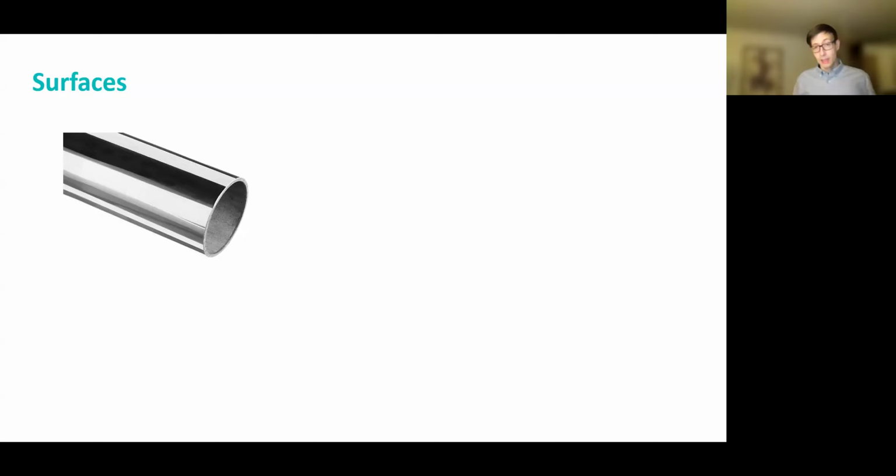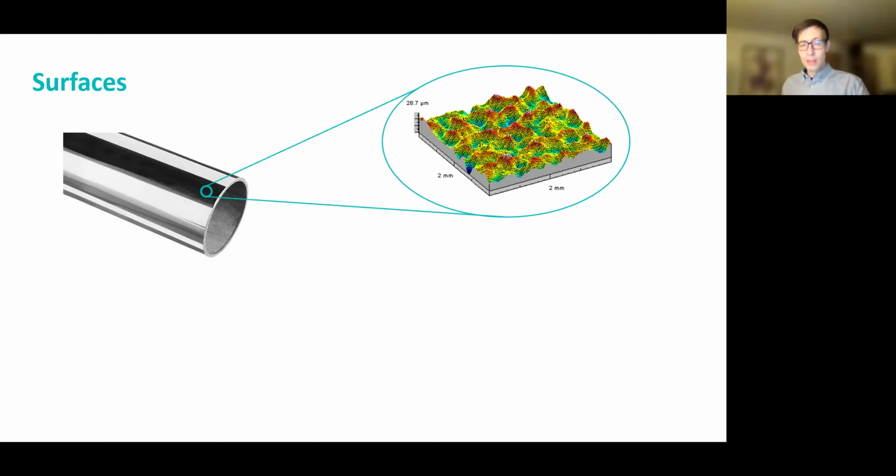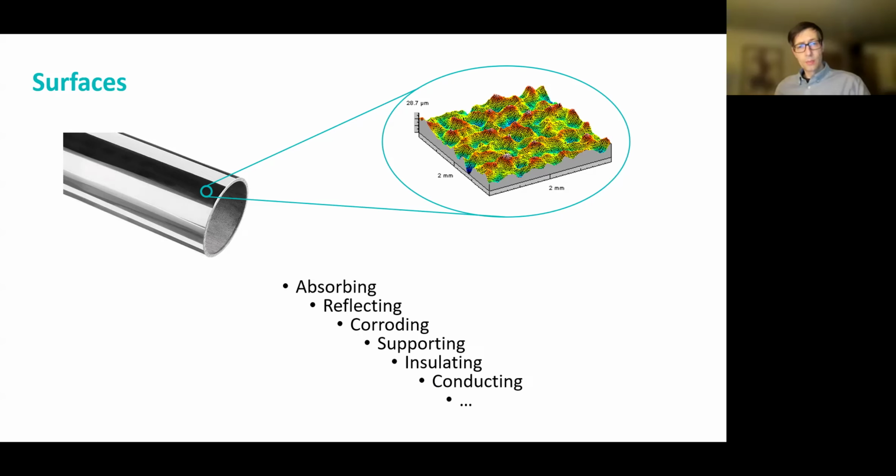So a surface like the work example here might look very nice, very shiny, very innocent. But if you look at it with some magnification, you will realize that there is some complexity. So starting with surface roughness, you realize that even if a surface looks like a mirror finish, there is some underlying roughness if you use powerful enough methods and instruments.